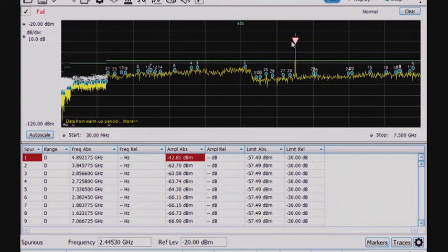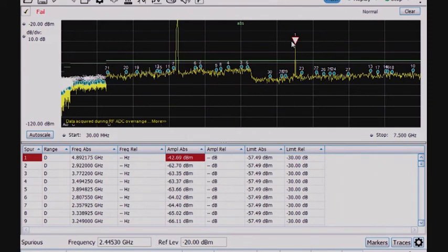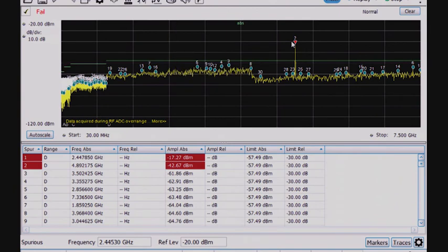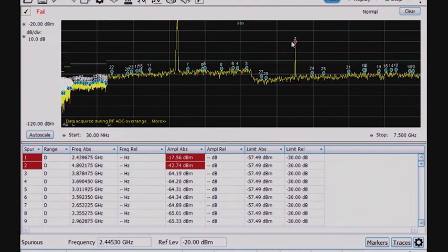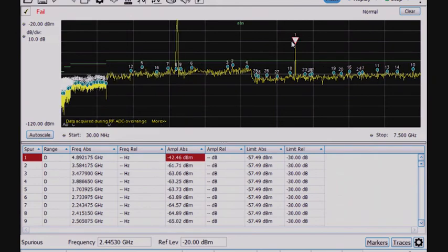But in general, a CISPR peak-based search is a much faster test and a more conservative test to make sure I have good confidence to go past final EMI compliance, so I don't waste time in the compliance lab. I can figure this out in my own bench, provided I have enough shielding and not any other signals present that might cause me to fail the particular test. So hopefully that gives you a little better understanding of how to use a spectrum analyzer to perform EMI pre-compliance checks to give you better insurance for passing final compliance checks for your device under test.